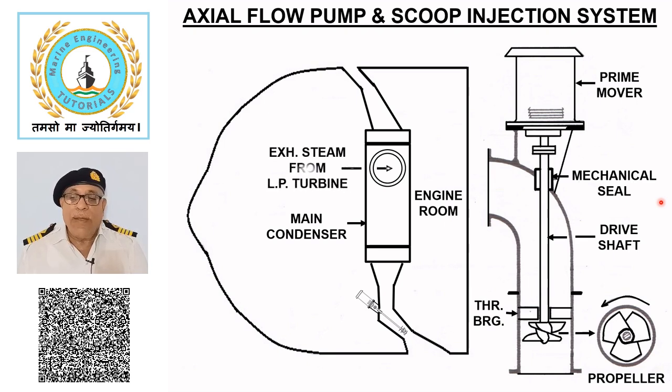Due to low pump head, the condenser is located at the bottom platform in the engine room and the flow of seawater through the tubes takes a single pass. Low pressure turbine is mounted on the condenser which directly exhausts the steam from the top of the condenser shell.